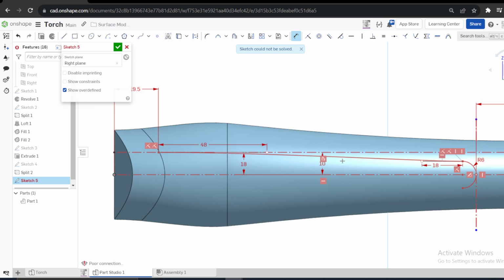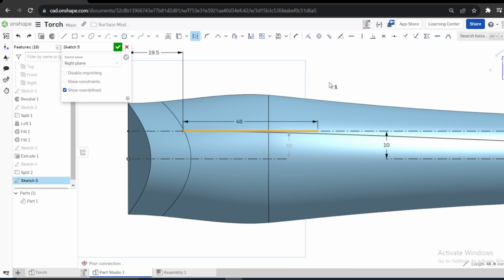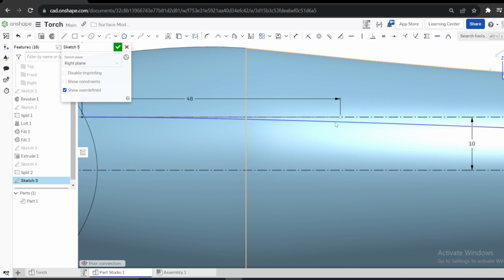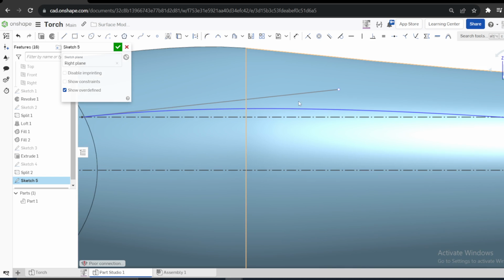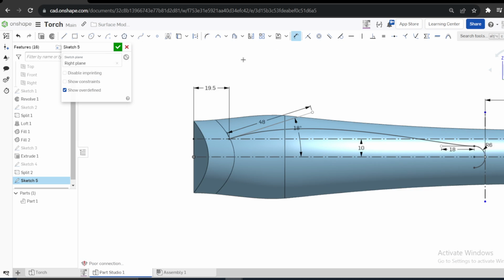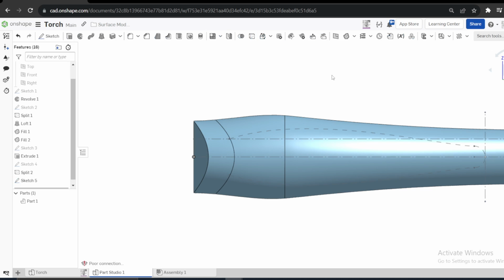To redefine your sketch, what's happening here? Okay, this one has a constraint. Delete this. It took an automatic constraint to be 18. Yeah. Then I want to mirror this sketch on this side like that. And that's my sketch for the side profile. This sketch, this and this.